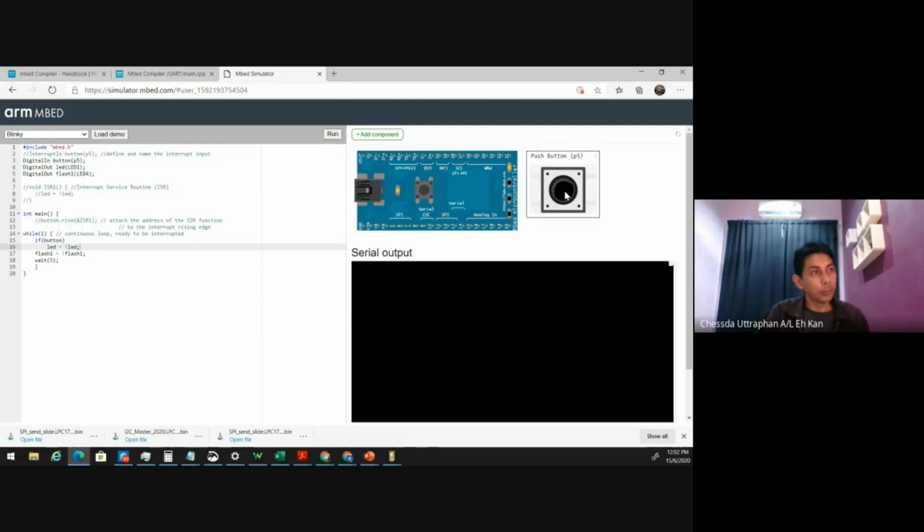Okay, you see, you press here. I press already. You can see this program won't work because when the program is inside this wait, it will not test the button. Instead, it tests the button only when you exit this wait function already.